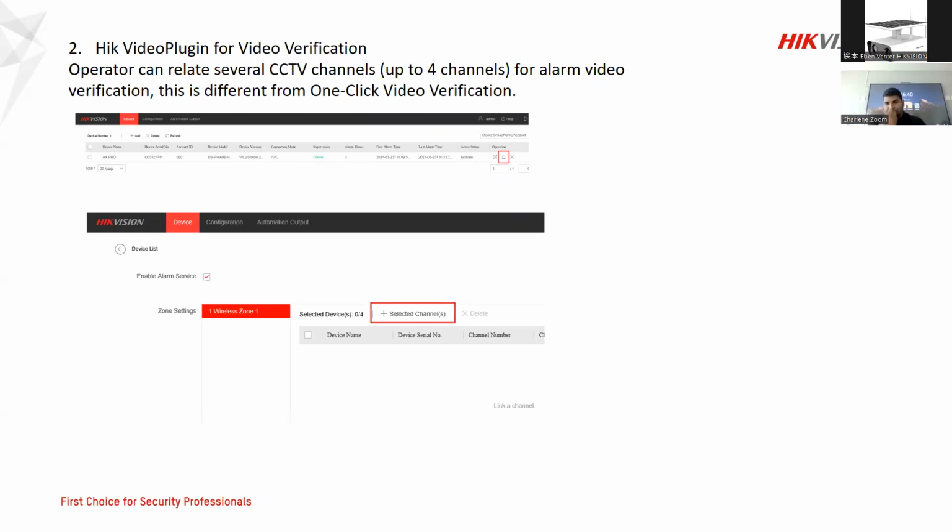You can also use your camera as a detector. So when you arm your alarm, you're actually arming your camera. If somebody walks through, the alarm will go off depending on what analytics you're running. With the Axpro, you run an intrusion zone or line crossing, and you can set up how you want to do line crossing or intrusion zone. It works very nifty and is quite a good tool, because now you have the ability to see what's happening, as well as have the alarm come through, and not after the fact, when somebody jumps my property and I have to go to the post recording to see what happened. You can actually see it live.